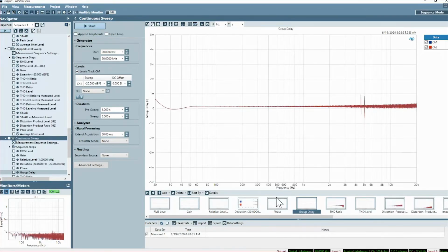I'd say that just generally, things we've seen that may cause errors in the impulse response is devices that don't have constant delay. Worst case imaginable might be a Bluetooth device where the actual delay of the device varies in time. Not having too much or too little delay. So in that particular case, I would suggest that we don't have an easy answer and we should reach out to that person and talk about their specific device under test.